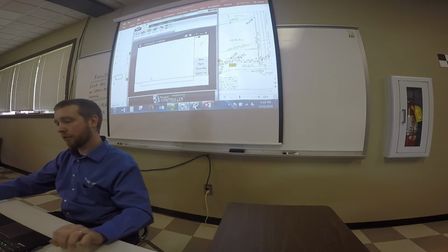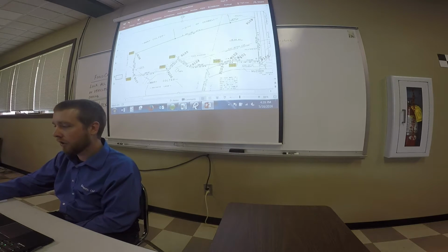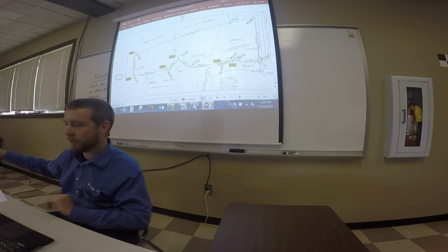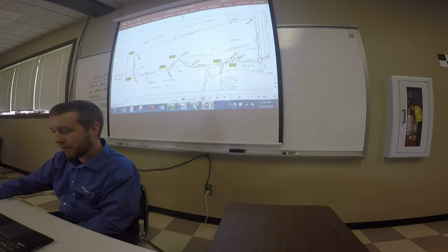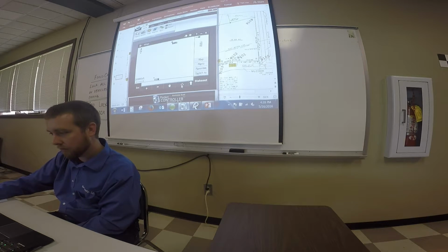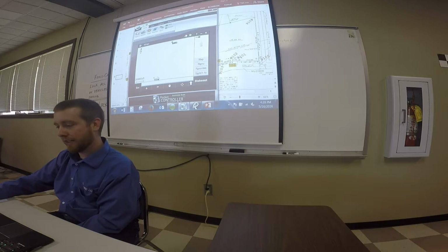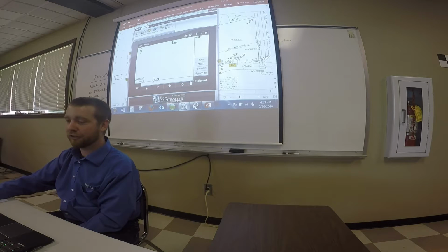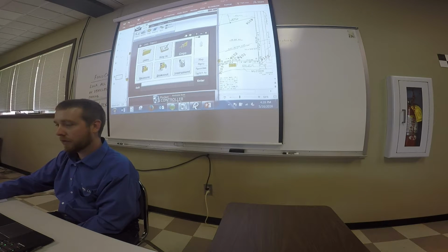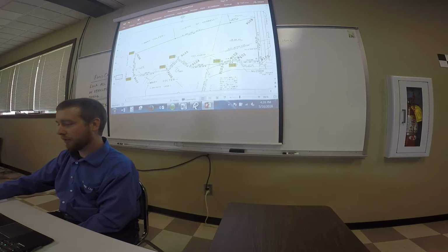What we want to do is take all these 9,000 numbers. Right now they're just floating off in space, on a totally different datum. If you look on the map here, here's our site, up here on state plane coordinates. Here are our 9,000 numbers, down here on 8,000, 8,000, just an assumed datum to give us something to start with. So we're going to take all our 9,000 numbers and drop them on 103.